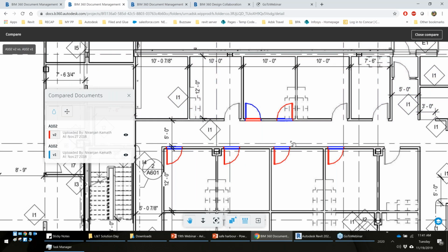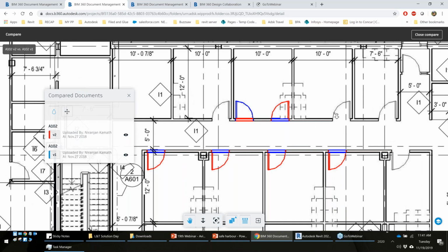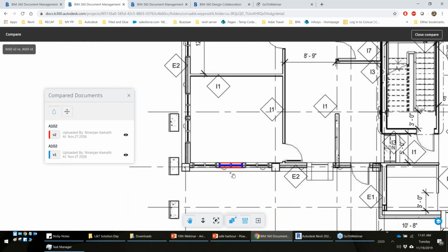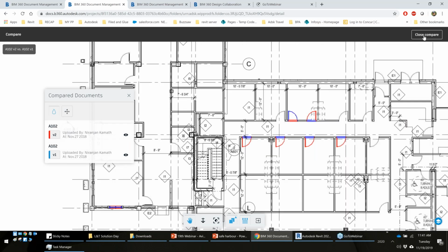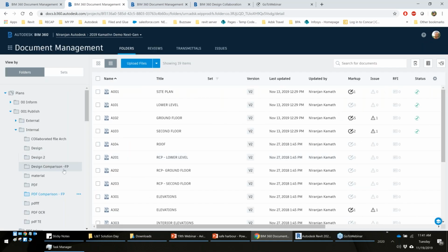But many times we always focus on the clouded areas which have been under communication, and we sometimes neglect and forget if a user by mistake has edited some of the windows also, or has by mistake deleted some more. So it lists down everything in that particular model if there are any changes, and you are least likely to miss that particular thing. Now, the next part is all the drawings that are there, like these could be my working models.